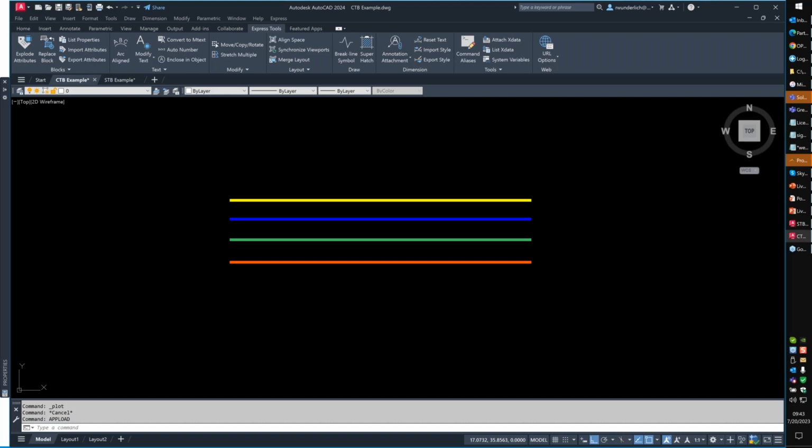I haven't experienced that. You may have something else underlying. We may have to do things like reset settings to default. We may have to go through and tweak a couple of settings for visual performance in both the Windows environment and in the Civil 3D environment. Sometimes that helps. We also need to see, is it with all drawings or some drawings? You might have something in one of the older drawings that's causing you the trouble. That would be probably where I would start troubleshooting that.